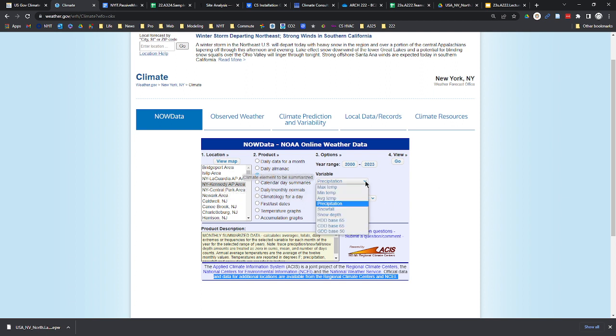Okay, but the main thing I want to do here is go to the heating degree day and cooling degree day inputs, or data sets. So heating degree day, HDD, base 65, that's a 65-degree set point. That's the temperature we want inside the building. And remember what I said, the heating degree day is simply this: the temperature I want inside the building is 65 degrees Fahrenheit. Any day where the average temperature is less than that is going to be a heating degree day.